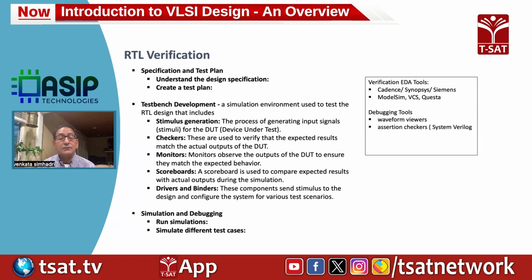After that, you have to develop the test bench that is used for simulating your design. A test bench basically includes stimulus generation. It's a process of generating input signals. We call them stimulus for the design and the test.